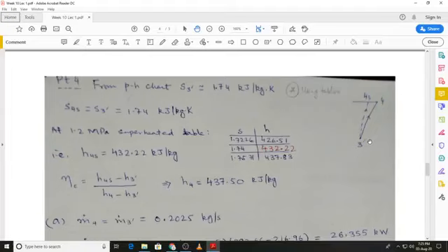As we had for the process of compression for the low stage compressor, similarly for the high stage compressor we have an actual process which is shown by the process line 3 prime to 4, whereas the isentropic compression would have been from state point 3 prime to 4s. And if we first consider the isentropic process, that is 3 prime to 4s, in that the entropy will remain unchanged, which will be equal to 1.74 kilojoule per kilogram Kelvin.